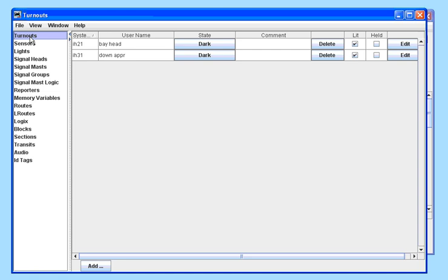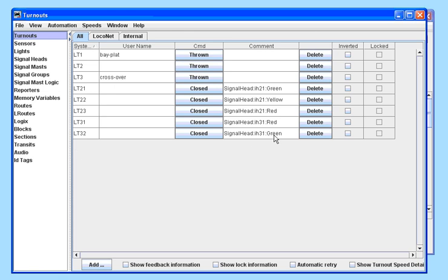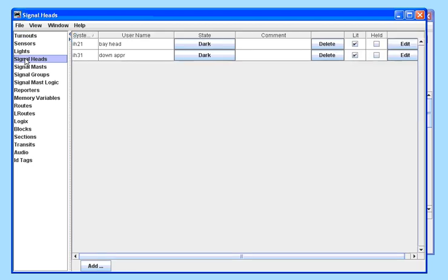This is because we need to change a little trick in the turnout table and invert the output of the green signal. This is the final bit of the wiring trick to get us to control the 3-aspect signal from 2 decoders rather than 3 decoders. So we've inverted that output, go back to the head, and if we flick through the states we'll find the signal behaves correctly.